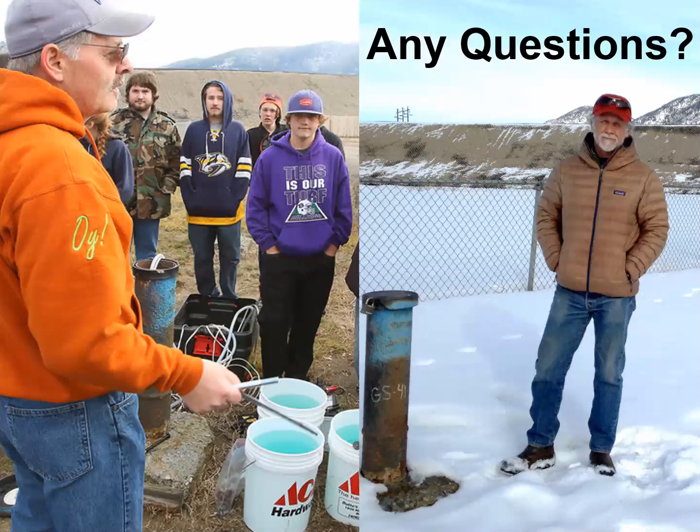And in the end, after seeing the sonic drilling, my idea was it was much more heterogeneous than I thought when we were drilling with air. And we're getting really just cut up samples, and it looked a lot sandier and gravelier. But the hydraulic conductivity going from 3 to say 600 was a big deal.